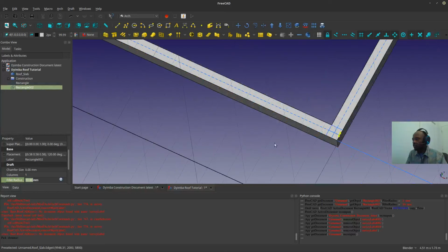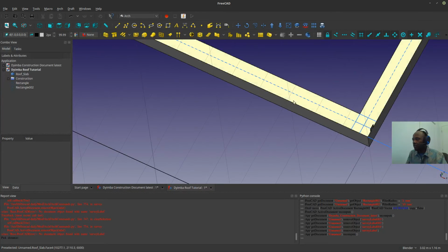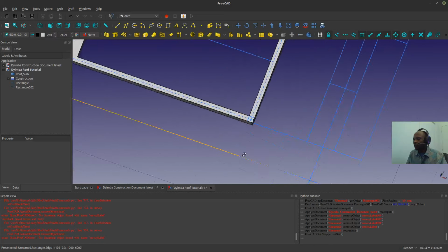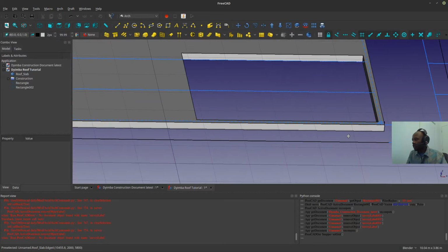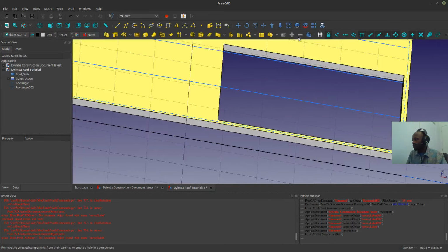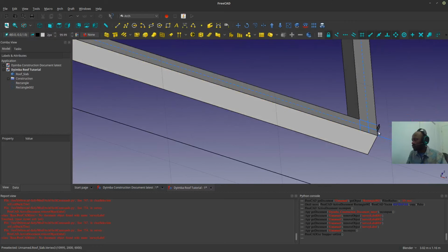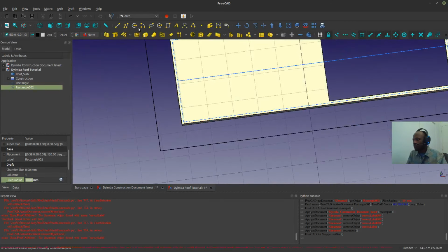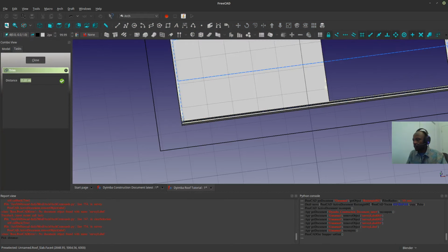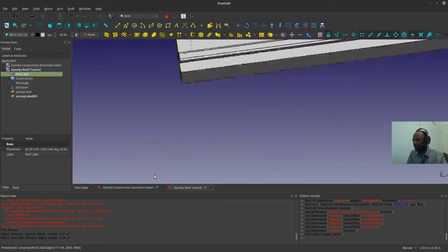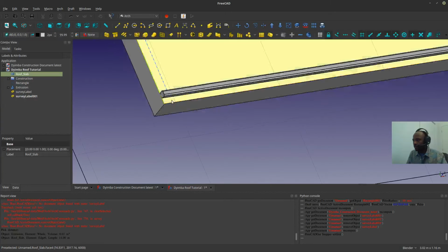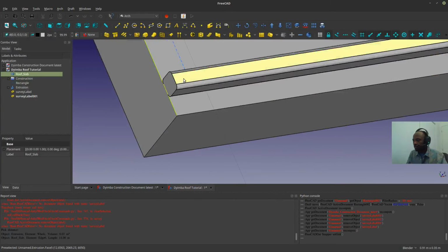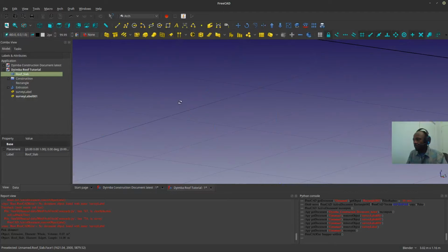Make sure to use that extrusion, change the face you're working on, select that face, and then make sure that you're in a plane that is parallel to the extrusion direction. So now I can extrude this, like this. Okay, we have something that looks good.